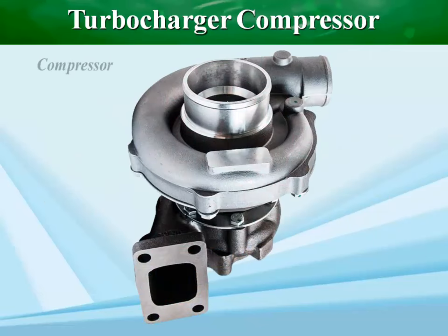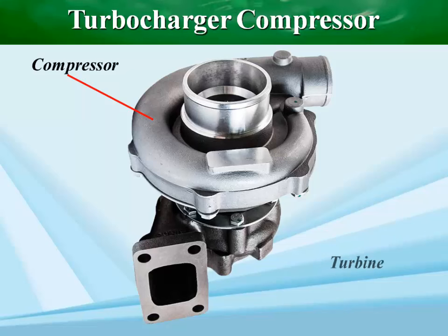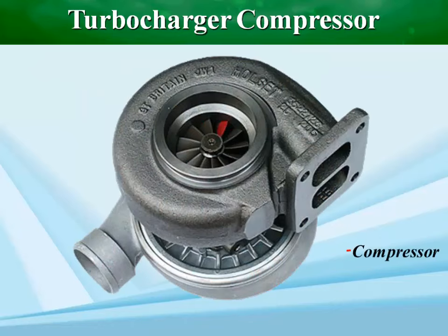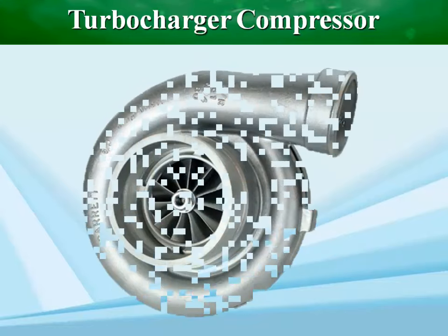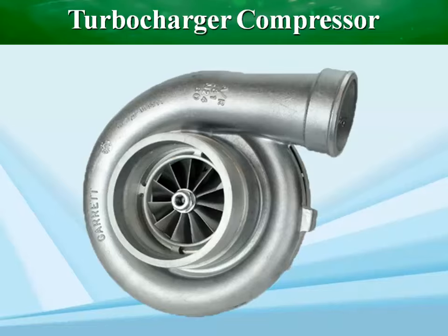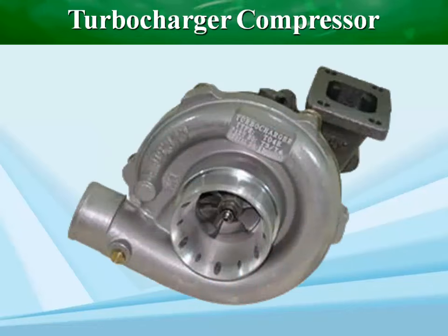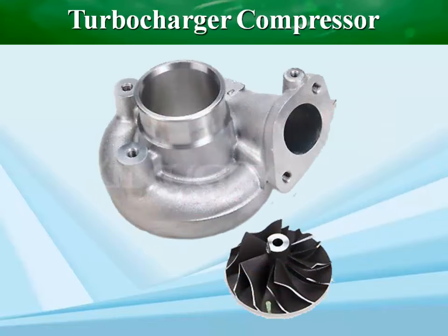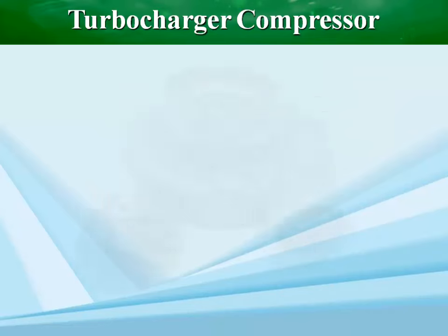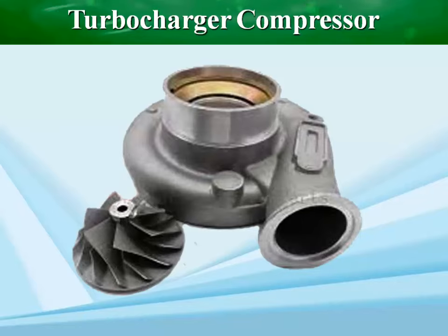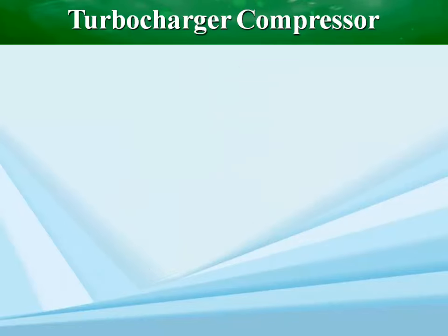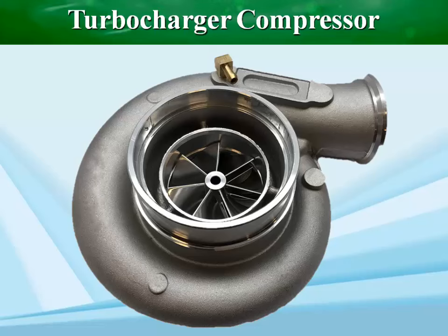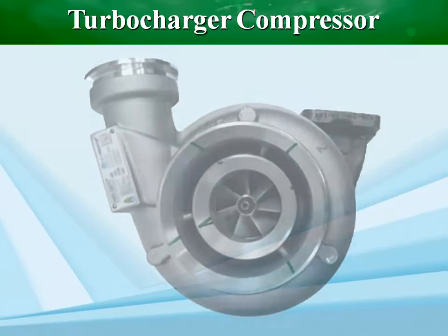The compressor is one of the 2 primary sections of a turbocharger, along with the turbine. Turbocharger compressors are generally centrifugal compressors. A turbocharger's compressor is the cold side of the turbocharger that draws in and compresses air to force more of it into the engine's combustion chambers. Driven by the turbine, the compressor increases air density, enabling the engine to burn more fuel and delivering a significant boost in power and torque.